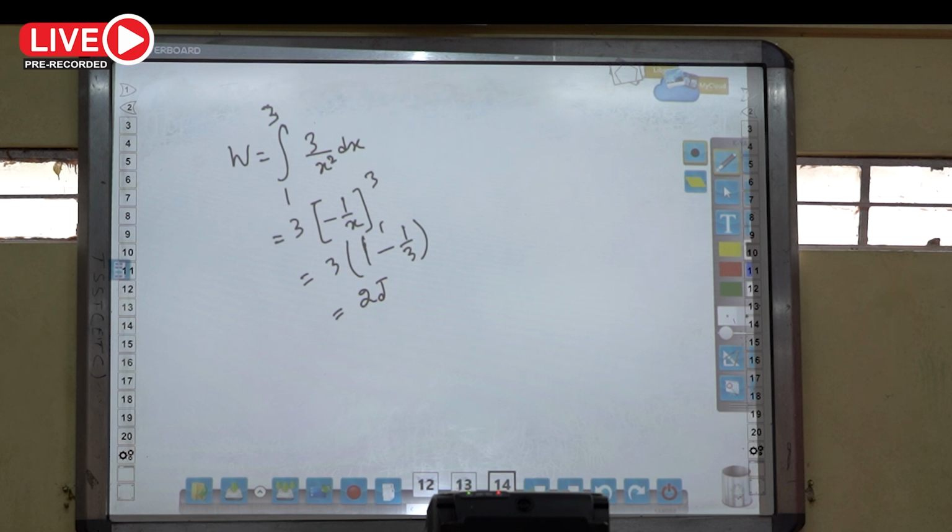So velocity increases and as a result pressure will decrease. So maximum speed and minimum pressure. Because velocity increases means kinetic energy increases, and then the pressure energy will decrease to maintain Bernoulli's theorem. The total energy remains constant at any cross section.